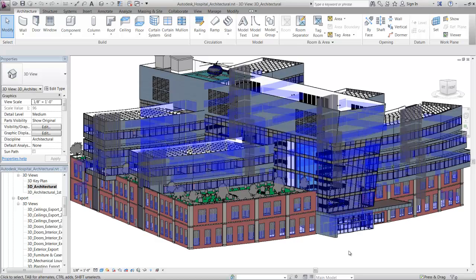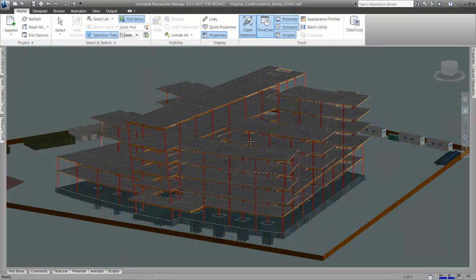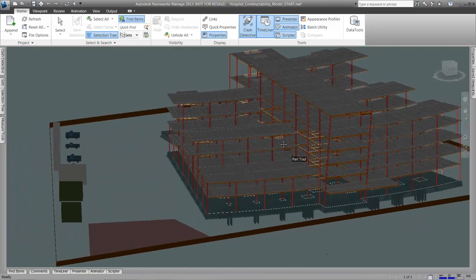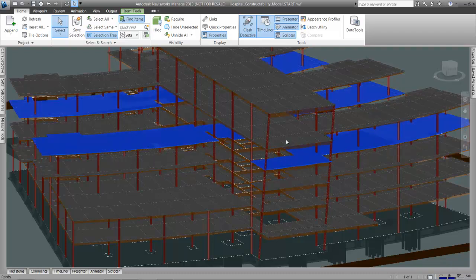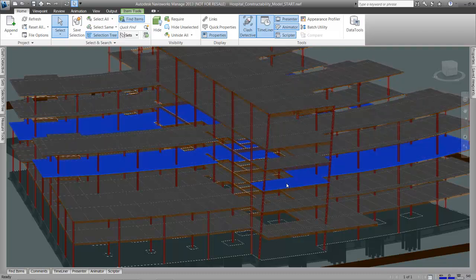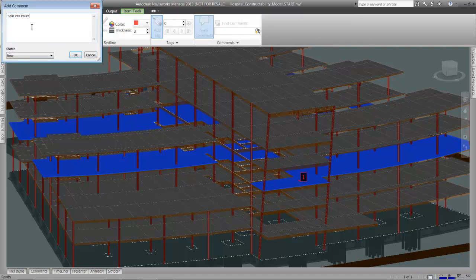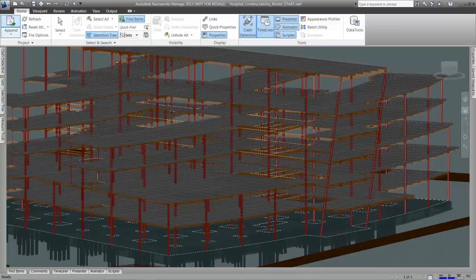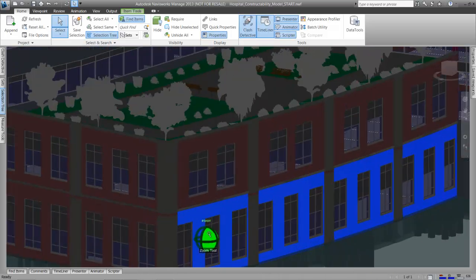Contractors often receive design intent models or simple documentation from the architects and engineers. However, in order to really have this information be useful and helpful in driving the construction practice, new levels of information have to be added to the process that account for needs and methods, materials, and how those project components come together. This is really the role that constructability plays. We can see here that the design model specifically needs to be broken down to account for concrete pours in the slabs, as well as breaking down the walls so they can be sequenced and coordinated appropriately.